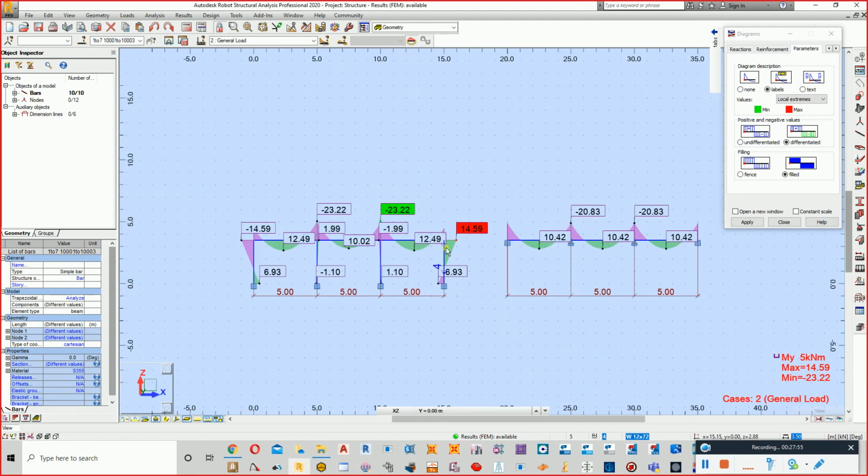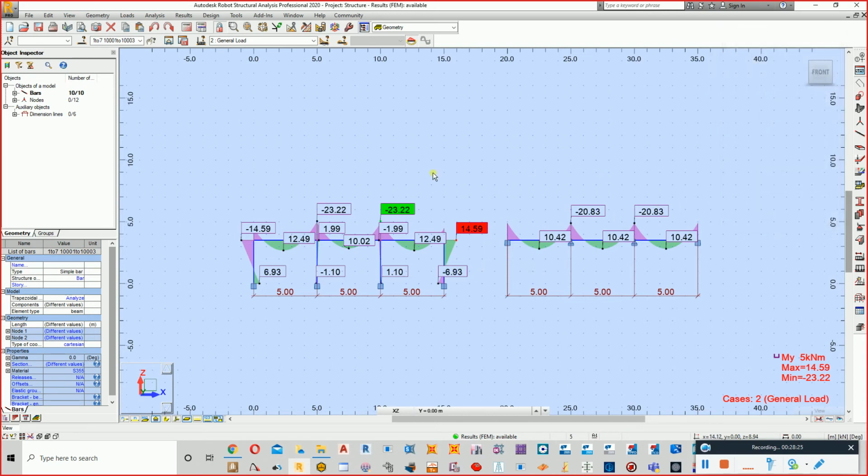So you should be analyzing your building as a frame, not as a beam. Once again, that's referring to the moment transfer. Your column should be taking a moment. Your element is not to be considered simply supported, or fully simply supported, so that the column will not take any moment. And once again, this is just to show you how to do the frame in